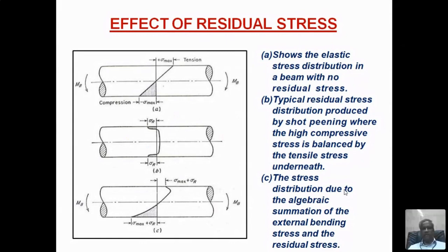And metallurgical variables, yes, fatigue strength and the tensile strength, there is a relationship, it is called fatigue ratio. Fatigue strength divided by tensile strength of the material. If you do both the tests, the tensile test and fatigue test, you find out this ratio. That ratio is an important parameter, and if tensile strength is high, fatigue strength is also high.